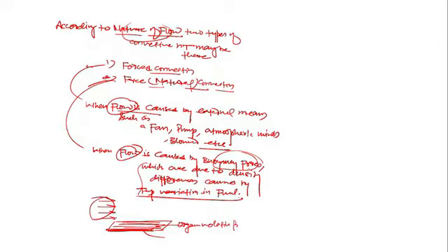Whatever, when the air is flowing over it, the paint molecules are volatile in nature, so they will diffuse into the air. Any air on the surface of the solid is of nearly low velocity or nearly stagnant. The velocity of air near the surface is stagnant, yes or no? So the concentration here is CAS and here C A infinity. C A infinity is the concentration of the diffusing species in the air.